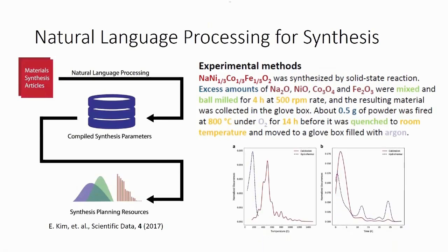if I were interested in growing titania, I could say, well, if I was going to do it hydrothermally, most people seem to anneal it below 200 C. If I'm going to calcine it, I'm looking at somewhere around 500 C with some excursions to higher temperature. And so now at least I have an idea of how people have done this before, where the unexplored places are, but also what's been successful in the past. And this allows me to make a cost-benefit analysis about whether I want to explore new synthesis techniques or exploit what's already available.